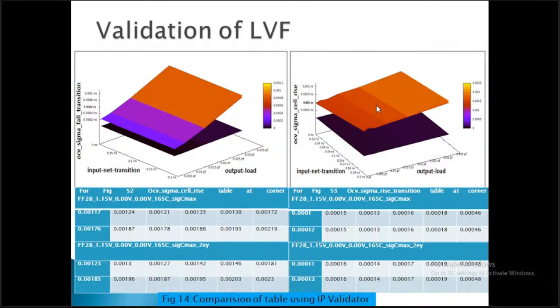So we put some stress on those devices or circuits to check how they will work over time. So there are differences. You can see that for the same point, it was earlier 12 delay, but later it becomes more. So there are some changes with time as well. We have to model everything at the start so that our chip works properly for at least 5 to 10 years.